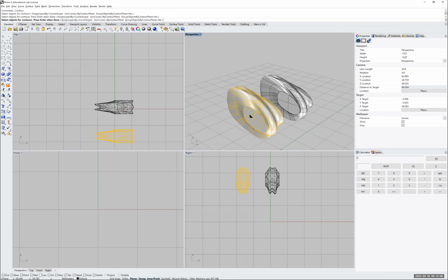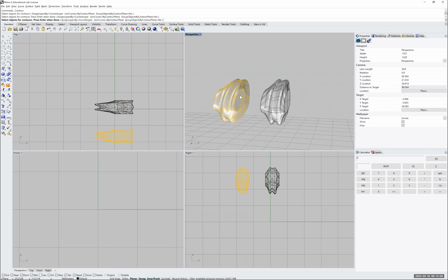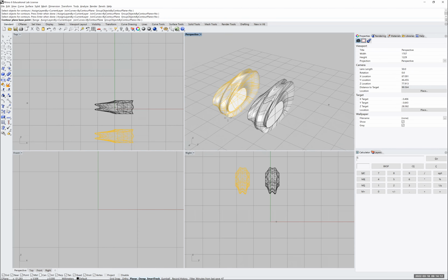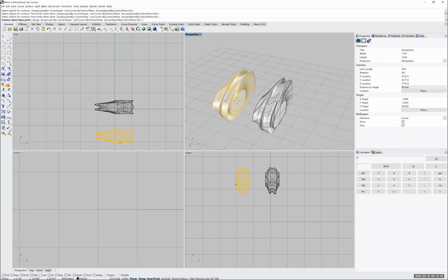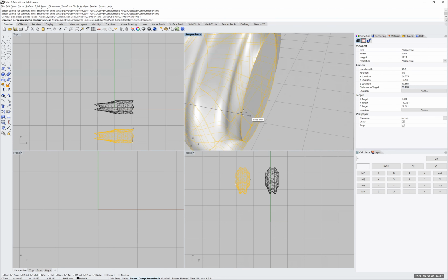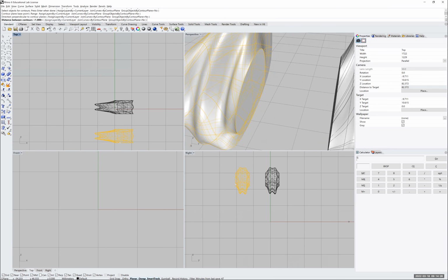So I'm going to select all my surfaces and all my objects. Once I'm done, I'm going to right click on my mouse, and then it says select the base point. So along which elevation do you want these curves to be divided? So if I want it vertically, then I have to choose this plane right here. Let's just make sure that I'm snapping to the right point. And I am. And then it says distance between the contours.